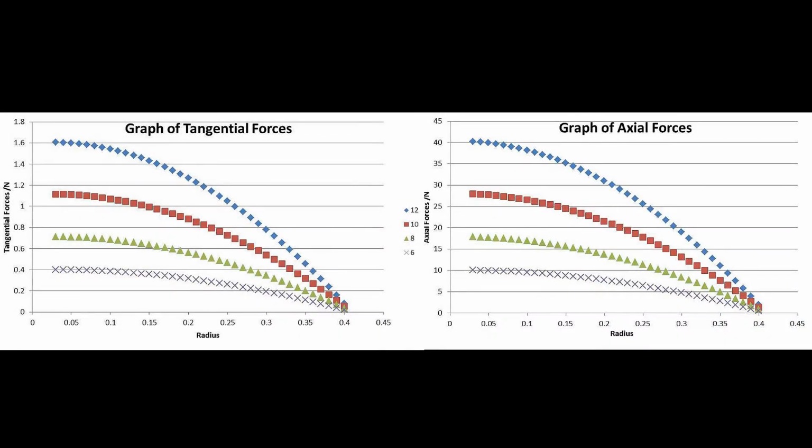We calculated relative wind velocities and values of lift and drag coefficients for each of the blade elements, which were then used to obtain their respective axial and tangential forces. Next, the engineer's theory of bending was used to approximate the blade as a beam in order to calculate the bending moments for the axial and tangential directions.